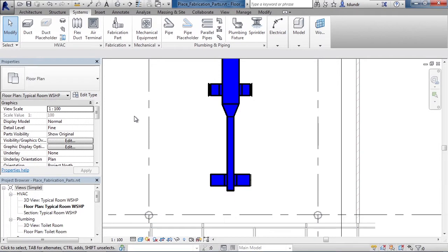As a review, in this lesson, we covered placing fabrication parts. We first talked about loading fabrication settings. If those weren't loaded, I referenced the previous lesson, Fabrication Settings, to load those in. Once the settings are loaded, you can choose what service you want, or services, and then run fabrication parts. We then looked at the fabrication part menus, basically the service and the groups, the options of those service and groups, and then how to drag and drop in place an element from the fabrication part menu.